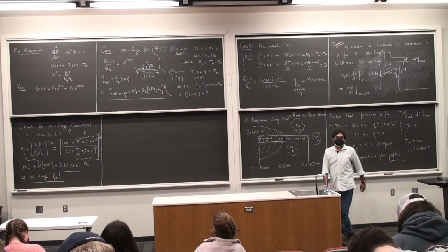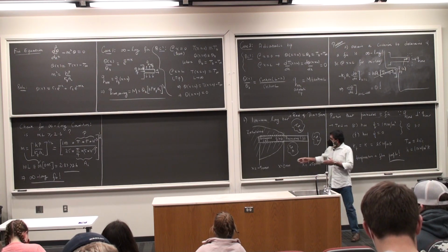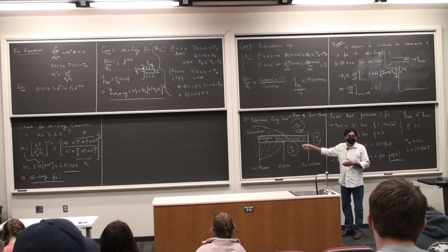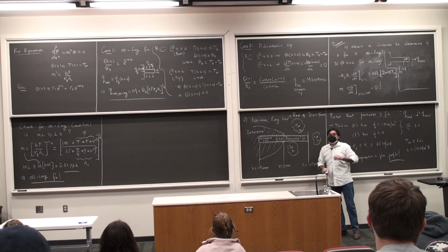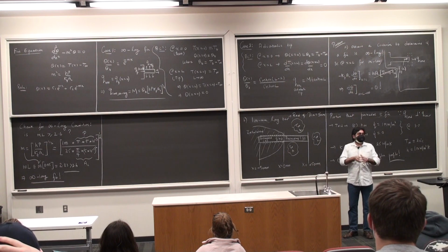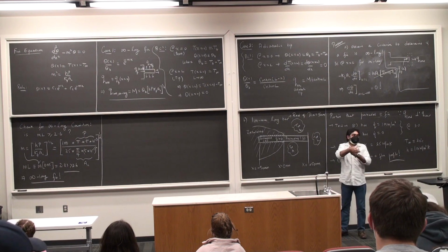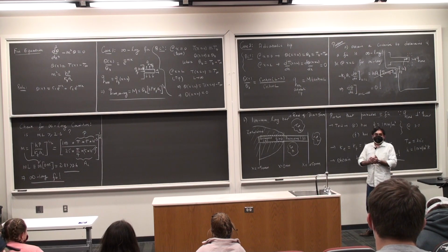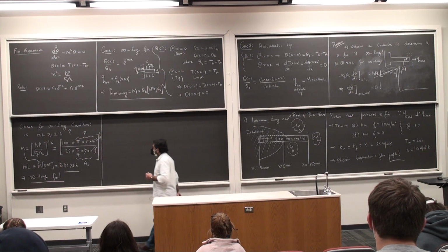And look at this. When we derived our fin expressions, we started off with x is equal to 0 and x is equal to L. So we cleverly also position our coordinate system. They don't give you the coordinate system to begin with. They just tell you the length of this creature is 100 millimeters. Half of that is stuck inside the wall. You set up the coordinate frame so that wherever the fin portion starts is x is equal to 0. And that simplifies the problem by a large amount, because we already derived all these expressions for the fin profile, and we just need to plug and check. Okay? Alright, so let's go for it.